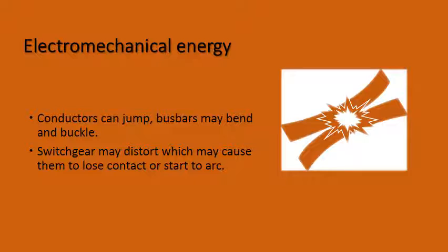In a fault situation, the magnetism around those conductors can be very, very strong, and in particular when there's two phases involved, they develop a magnetism which is pushing them apart very, very strongly. So they might rip from insulators and touch the metal of the casing, or they might touch another phase, and you're going to end up with a massive explosion or a big short.